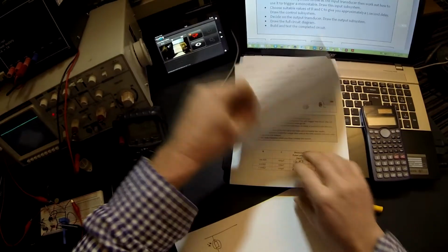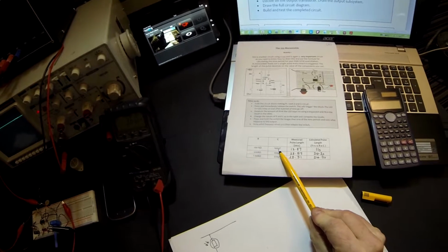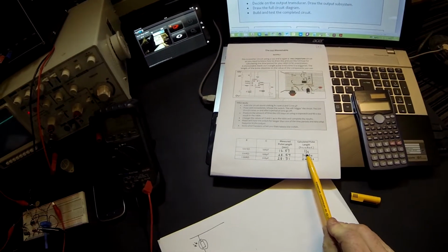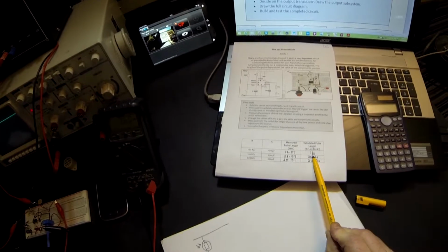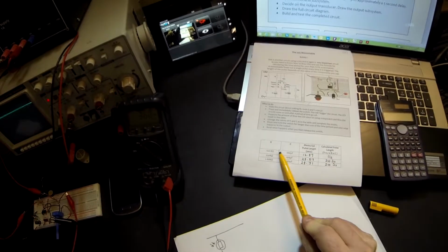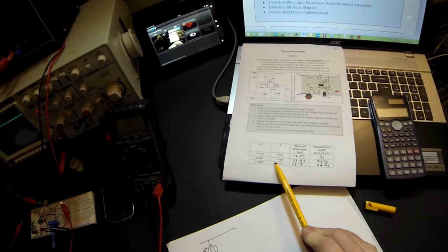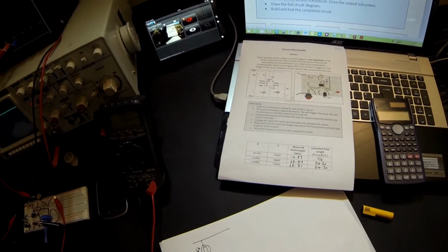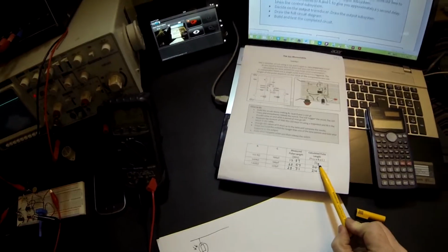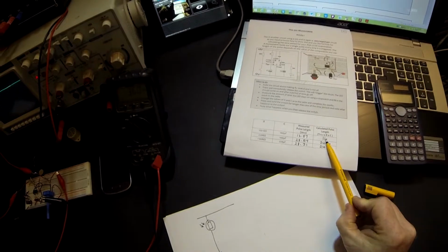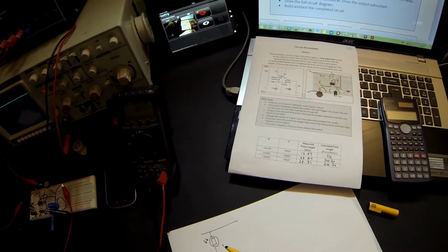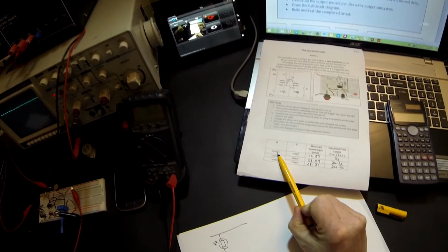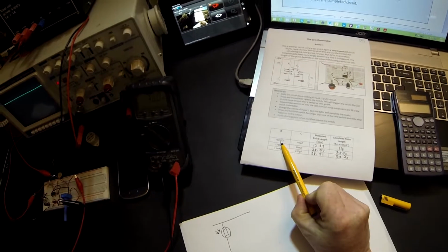Now if I go back to our original results, we can see that if we used a 100k resistor and a 100 microfarad capacitor, that gave us a time delay of 11 seconds, and we want about half that. Now we also know that when we doubled the value of the resistor, or we doubled the value of the capacitor, we doubled the value of the pulse length. So by definition, if we halve the value of the resistor or halve the value of the capacitor, we should halve that pulse length. So why not change the value of resistor, because we have far more of those available,